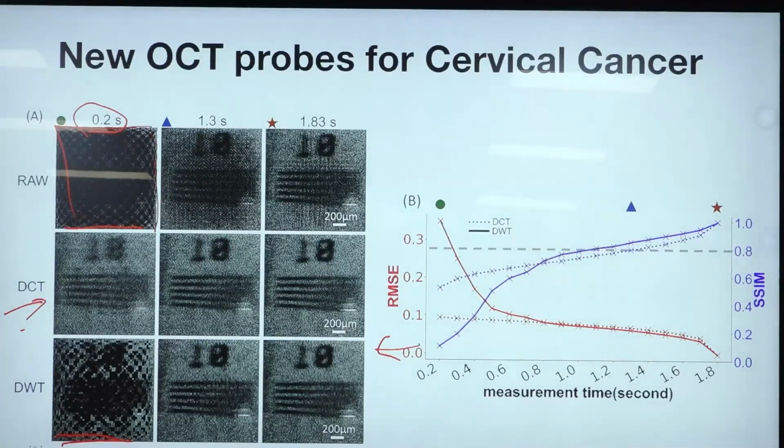That's called sparsity. So after which transformation will there be the smallest number of coefficients? The discrete cosine transform, DCT, is a good transform for this purpose of data processing. We tried several different transforms and approaches, and these are some of the better ones which we found.